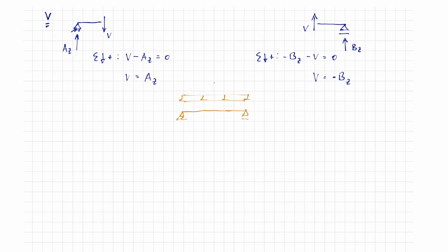In the case of a single span beam, where the resultant acts precisely in the center, the support forces have the same size and the same algebraic sign. Each support thus carries half of the resultant, or rather, QL/2.